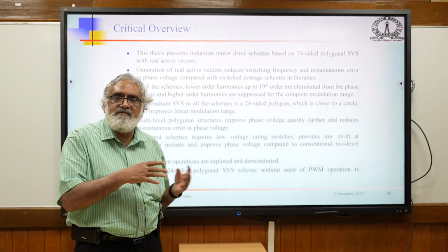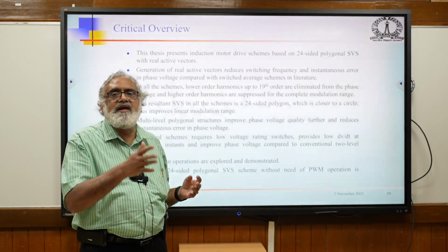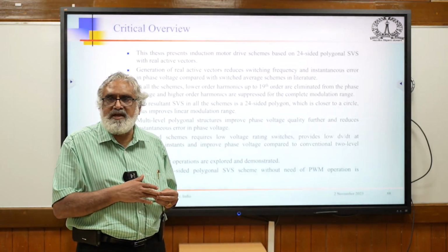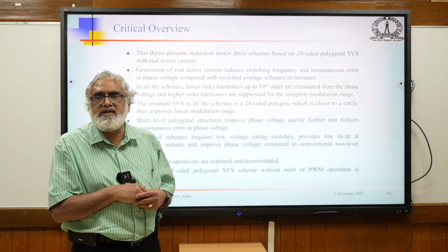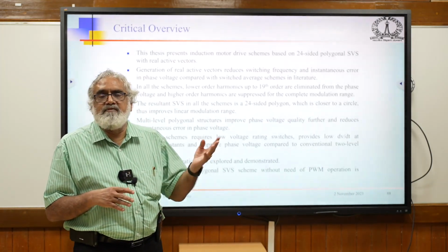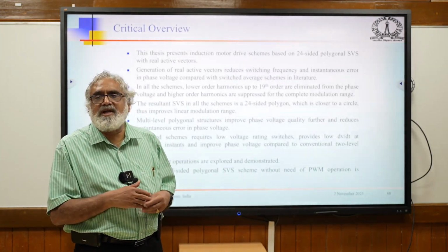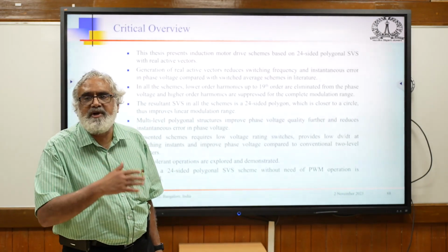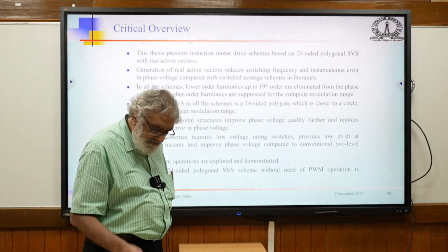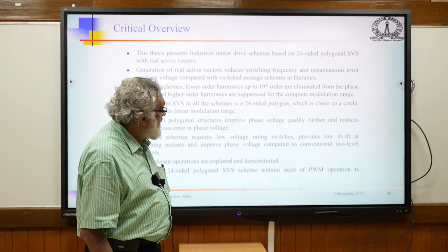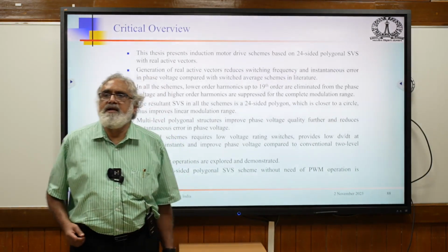The advantage is that at the same time, in the extended linear modulation range, the region belonging to the over-modulation range of the conventional inverter, the 5th and 7th order harmonics are absent throughout. We are still in the PWM modulation range. That's the thing we are doing now. Thank you. I'll stop here.